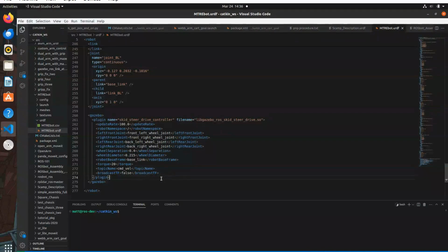And so that's going to help us here in terms of actually being able to control this with something like, well, you can just now send any twist messages you want. So you can generate twist messages from your LiDAR script, or you can generate twist messages just from a regular Python node if you want to. And there's a bunch of things. So we're just going to use teleop twist in this first example because that's really straightforward. But there are things that we do need to change.